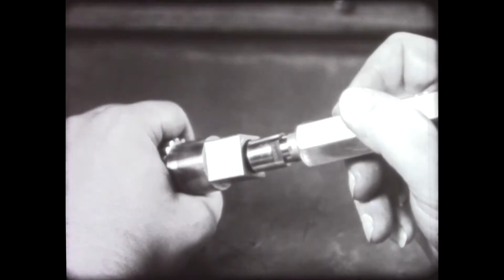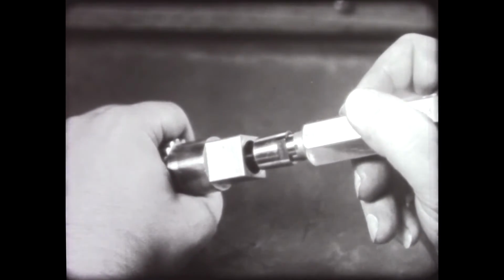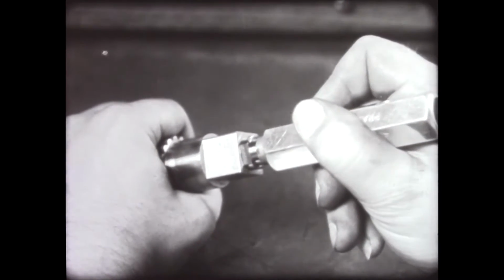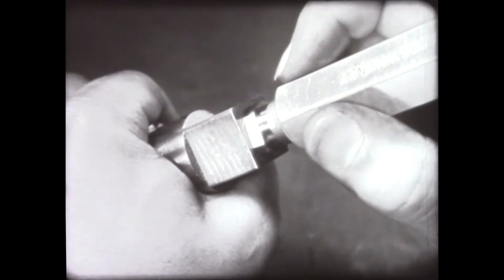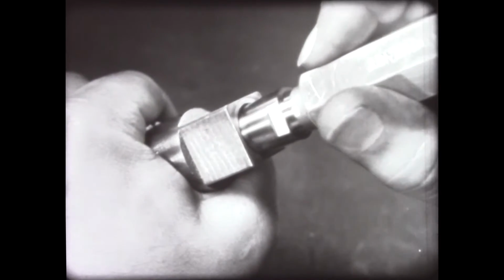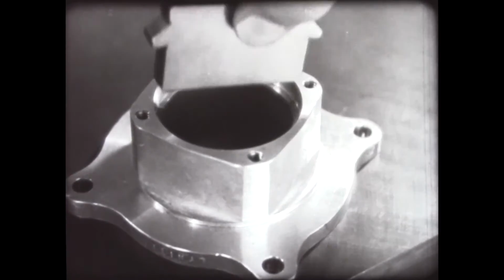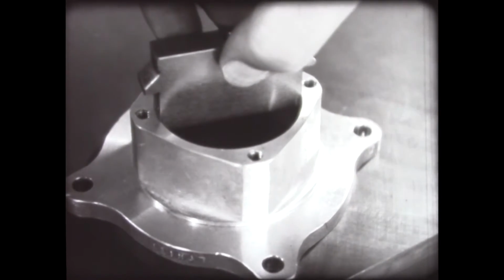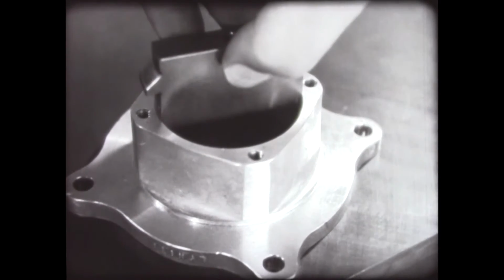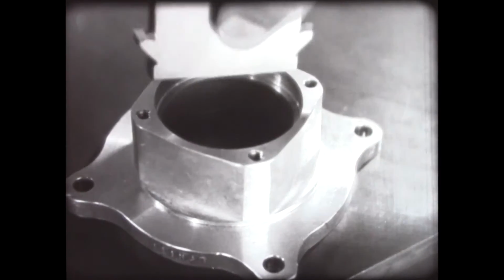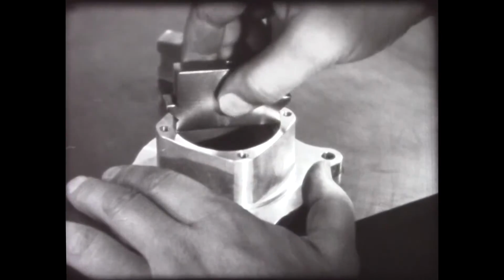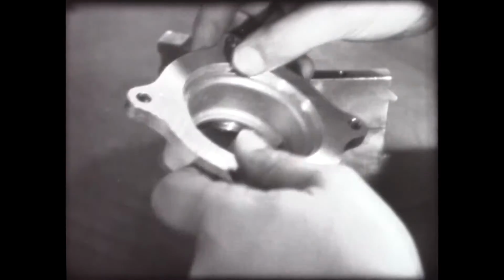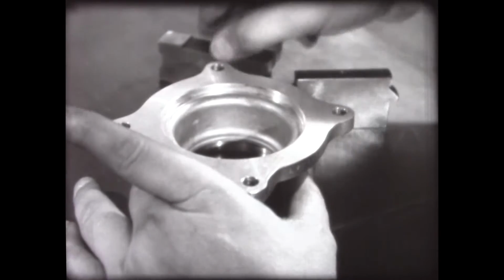Taper plug gauges are made in a great variety of sizes and angles of taper. The limit mark on this one is in the form of a flat. A widely used type for checking internal dimensions is the flat plug gauge. Go and not go gauging members are on opposite ends. This type is particularly useful in gauging large holes. Its light weight contributes to ease in handling.